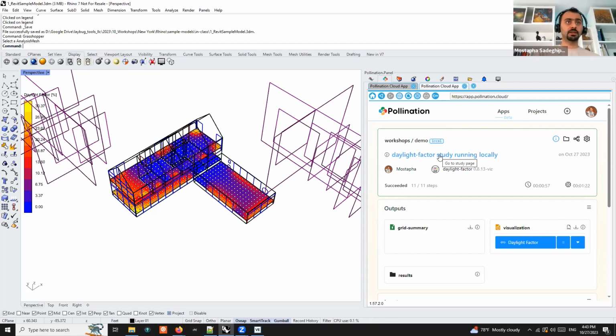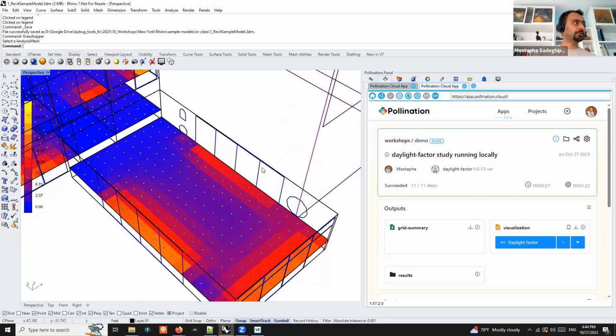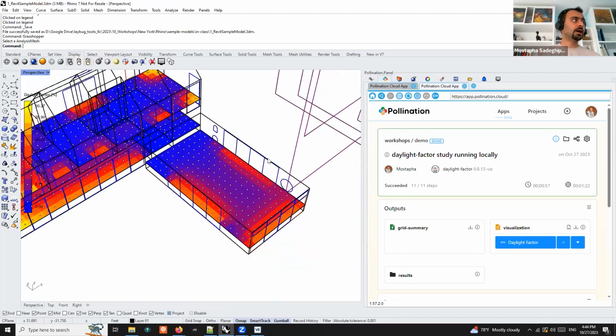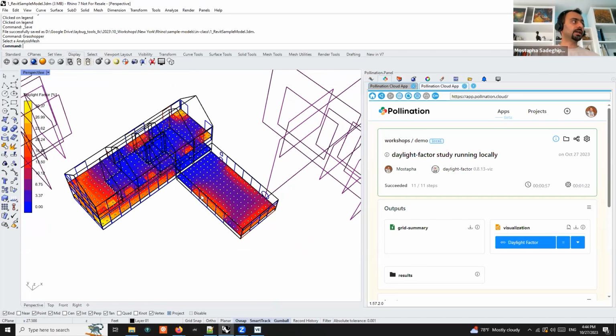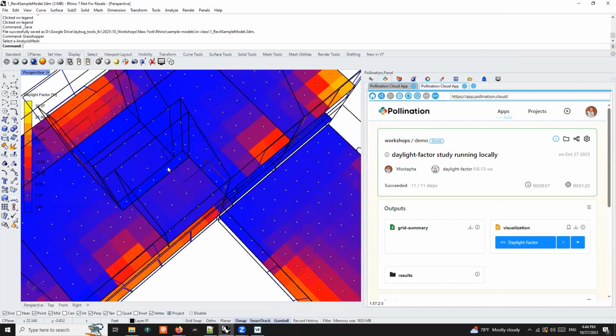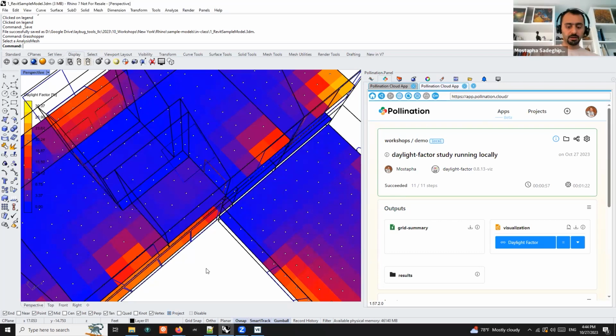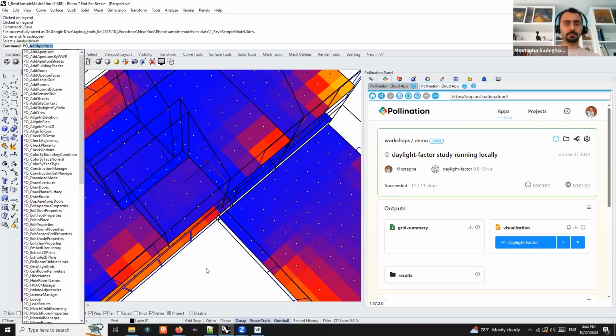The reason you will need them to be room-based is that, I should say, for LEED option 1, we have to do a post-processing calculation for all the dynamic blinds. Because of that, we need to know which sensor grid is part of what room. So if you want to only run for common spaces, for example, for this shaft, you don't want it included in the daylight study, you just remove the sensor grid from that area.